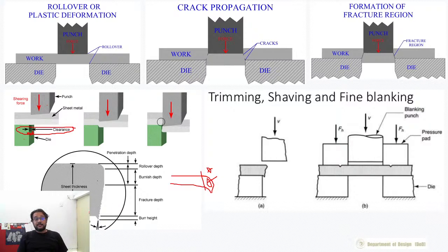And when the material is cut, it's not like a straight edge. That's important, because when we are designing in, let's say, CAD, our edges are always flat, like 90 degrees to each other. But in reality, this is what you will see at the part where it is cut. You would have this portion which is pressed by the punch first, and there will be a straight section, the burnished section, where there was the largest friction between the material and the punch, and there will be a section where the tearing of the material happens. This diagram shows what actually happens as the die goes from stage 1 to 2, and then to 3.